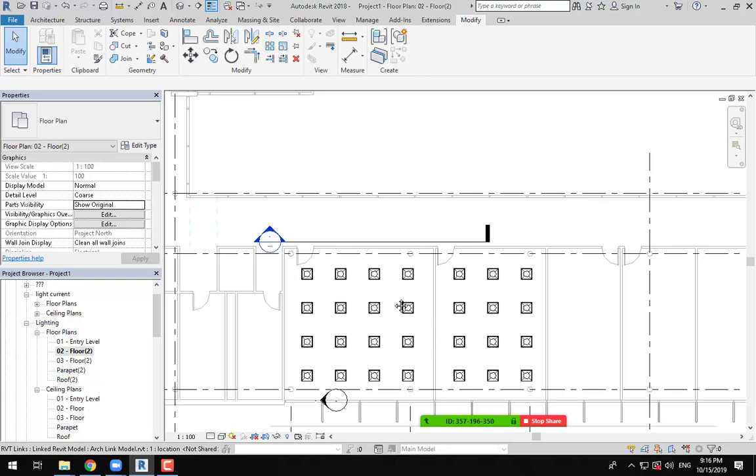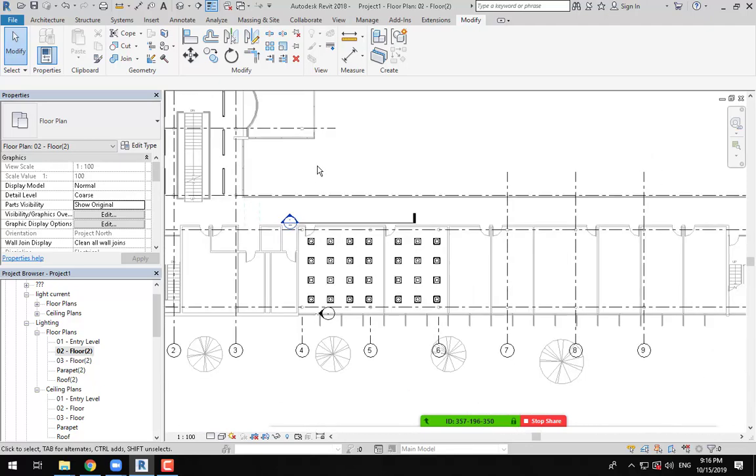It's according to the volume of the room the lighting will fill. So we need to create spaces through Revit, and after that we can export something called a gbXML file to Dialux or Dialux Evo, make the calculations in Dialux or Dialux Evo, and return it back to Revit with the final values. Okay, so how can we create spaces?